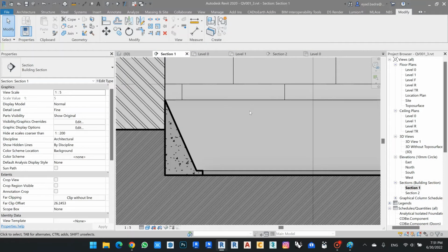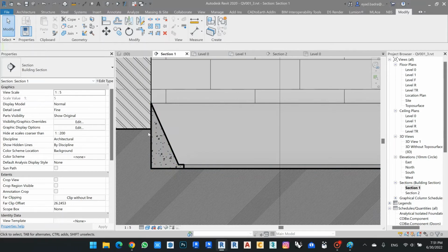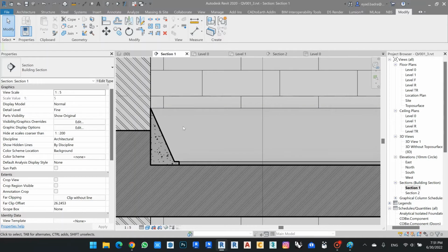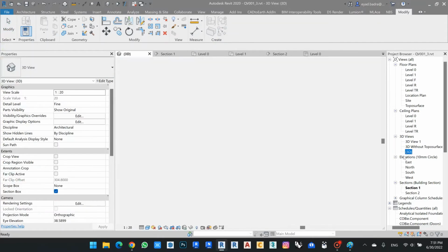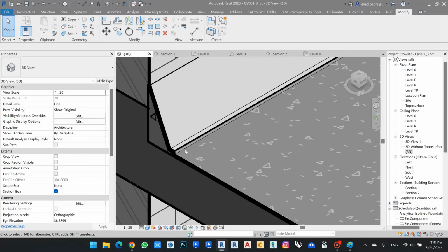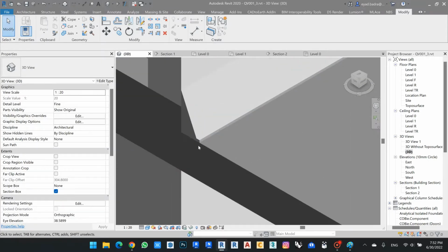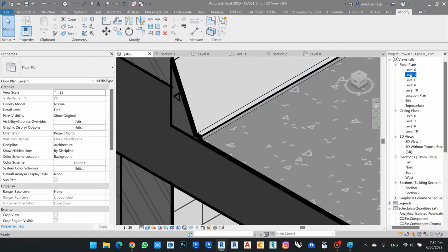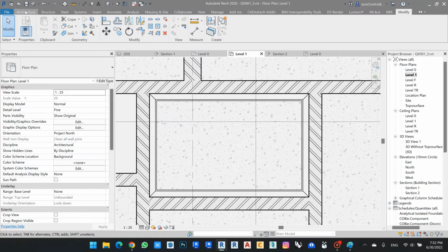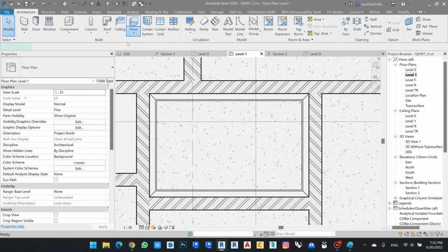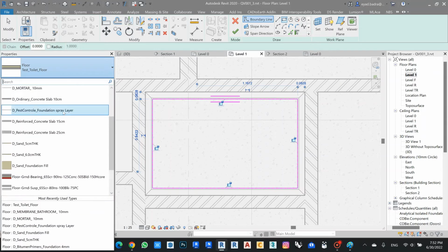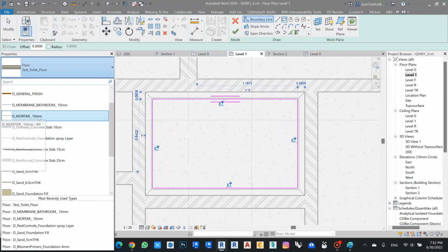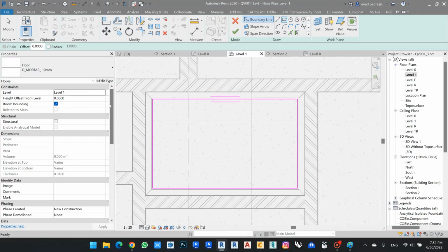And click Finish. So as a beginning, this is my first layer. Then we will start to make the flooring to connect this layer. If I go now in my 3D, I did it just in this way, but I now need to complete my 1 centimeter thickness for the mortar, so I can go from here and start to make a normal architectural floor. I will choose here, I already made my mortar layer of 1 centimeter, 10 millimeters here. Click OK.